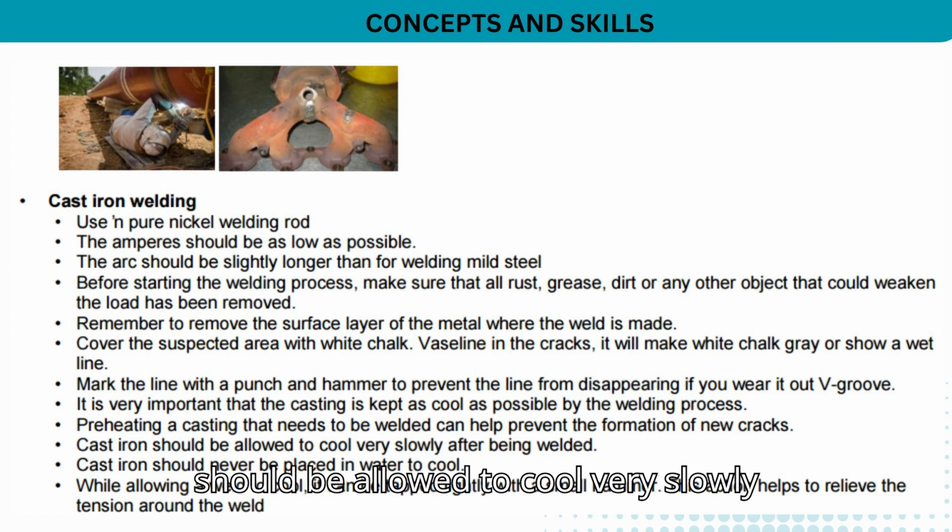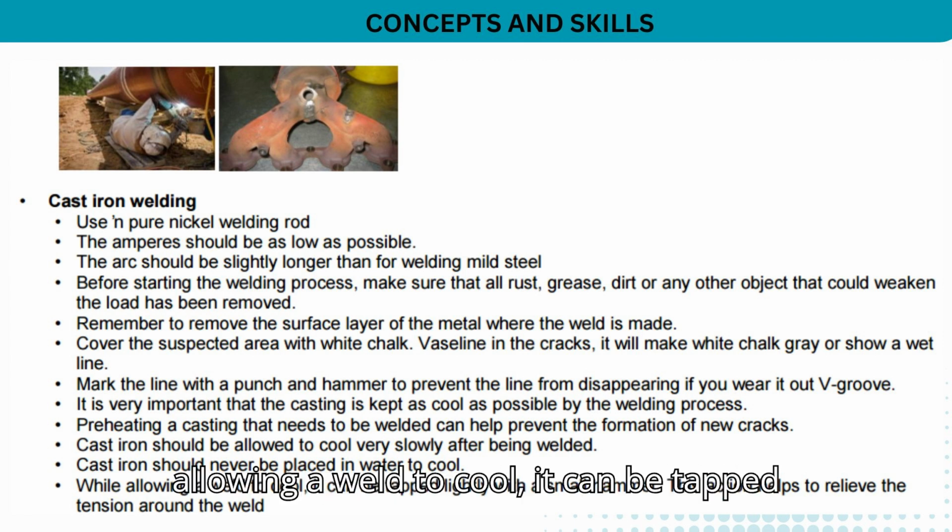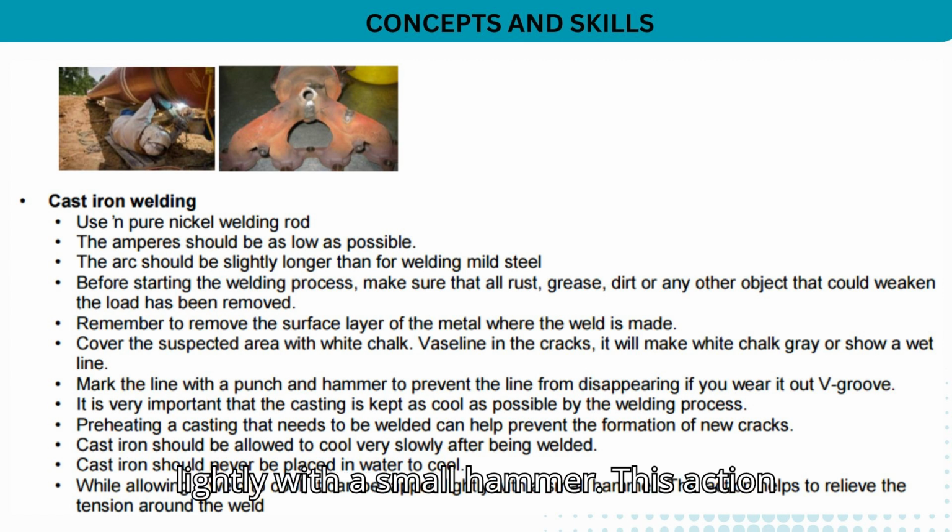Cast iron should be allowed to cool very slowly after being welded. Cast iron should never be placed in water to cool. While allowing a weld to cool, it can be tapped lightly with a small hammer. This action helps to relieve the tension around the weld.